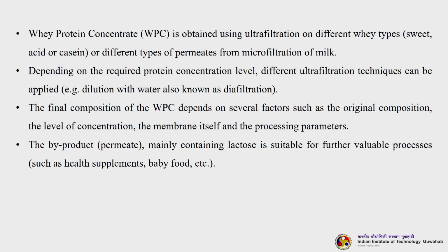So, whey protein concentrate is obtained using ultrafiltration on different whey types, so sweet, acid or casein. There are different types of whey that are coming out of the cheese manufacturing process or different types of permeate from microfiltration of milk. Depending on the required protein concentration level, different ultrafiltration techniques can be applied, as for example, dilution with water, also known as diafiltration. So, the final composition of the WPC depends on several factors such as the original composition, the level of concentration, the membrane itself and the processing parameters.